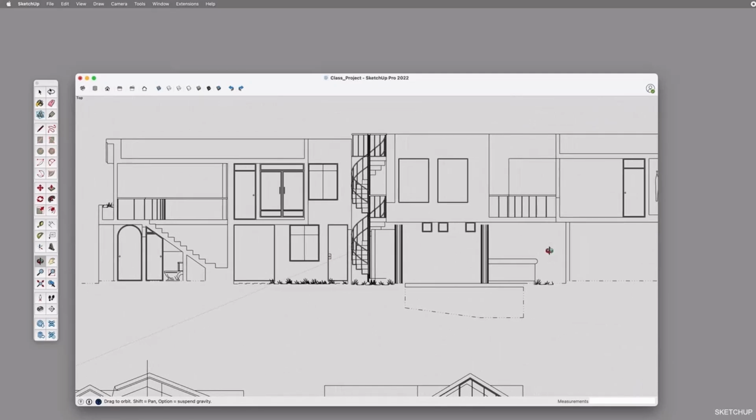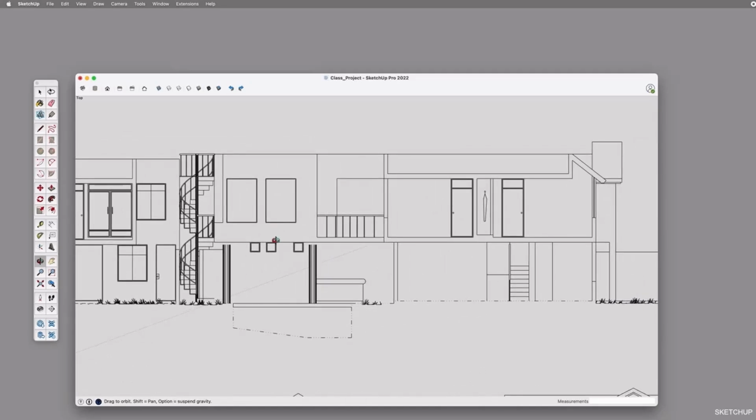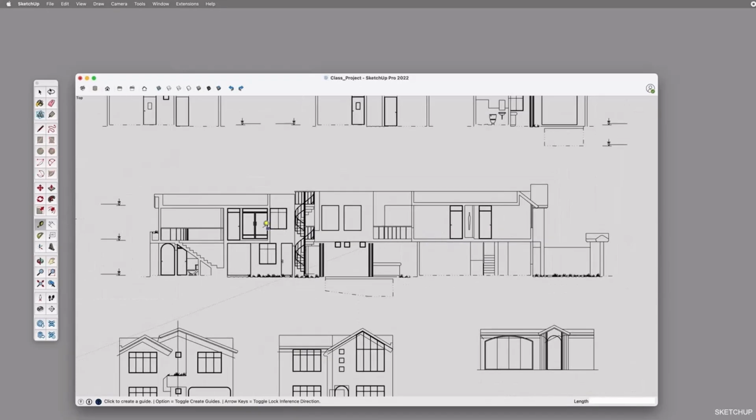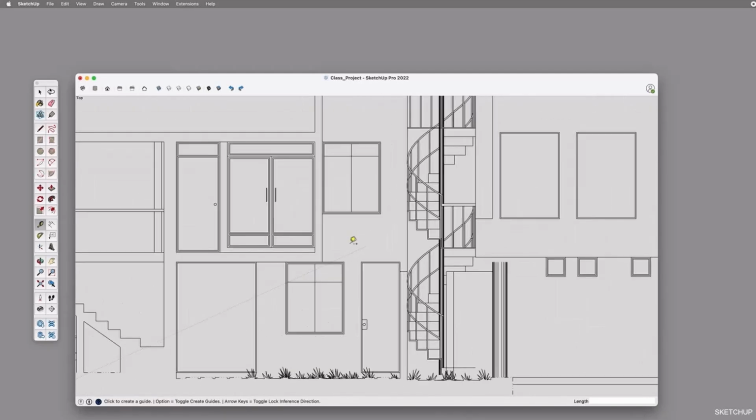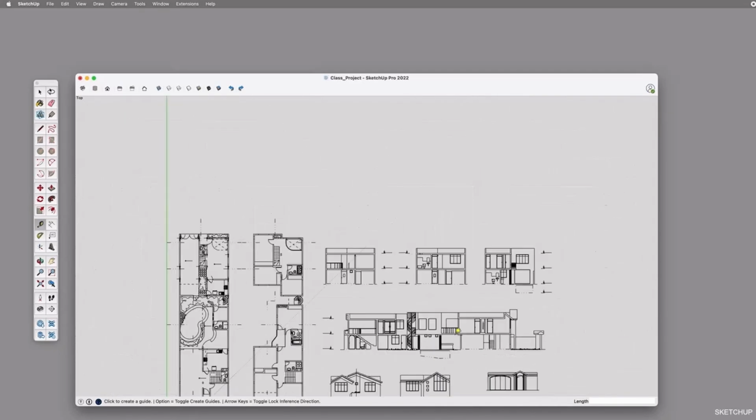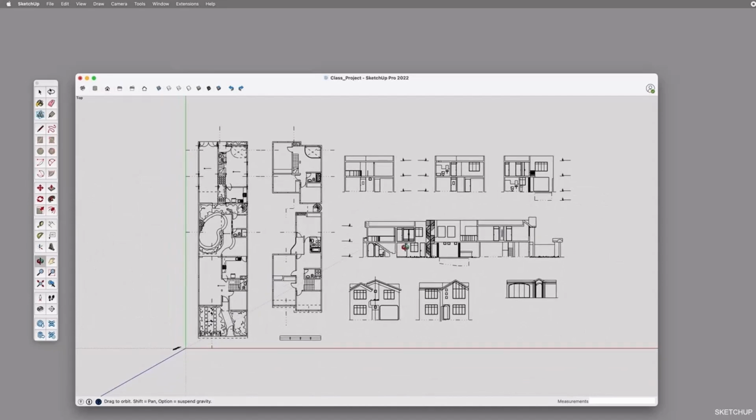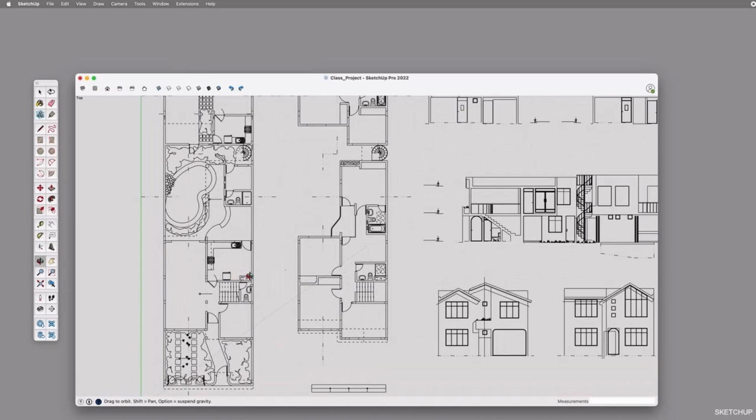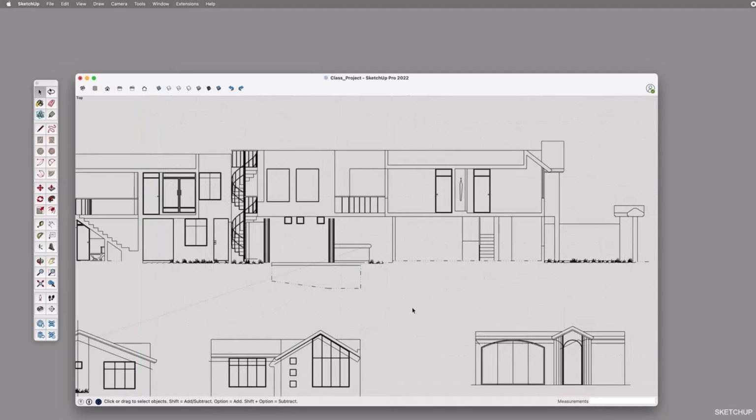But what can be important are, for example, the window heights. In case you are provided with a CAD file only, this is the only way you may be able to see how much space you have underneath or above windows. Sometimes I use the frame of the walls if they are clean. Just expect that with those CAD files, you may have to clean them up first before being able to actually use them. One of the first things I do is check my scale and see, for instance, if my ceiling height is correct or any other measure that you may have.